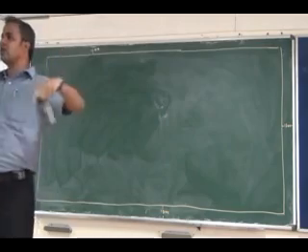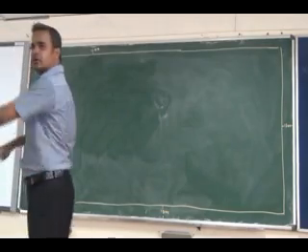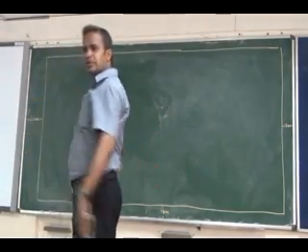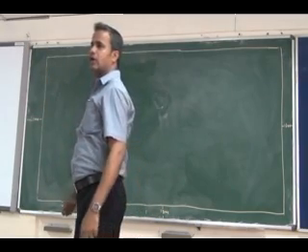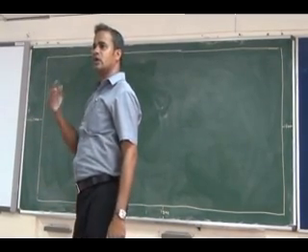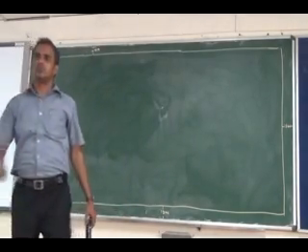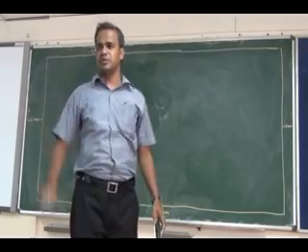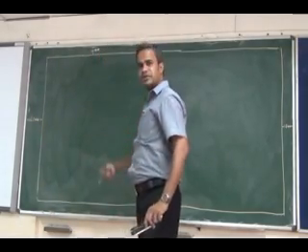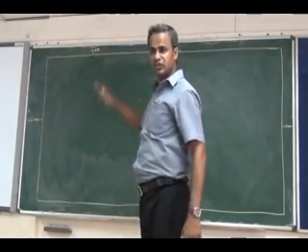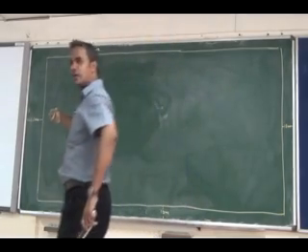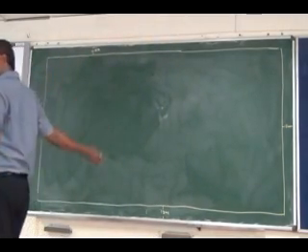Why am I using a color chart? The layout should be a dark one in your A3 drawing sheet. It should be drawn in a dark pencil. We are going to see about pencils. The dark pencil you are going to use is an HB pencil. So using an HB pencil, you can draw this layout. You should have a 20 mm gap on the left side, and on all other three sides a 10 mm gap.